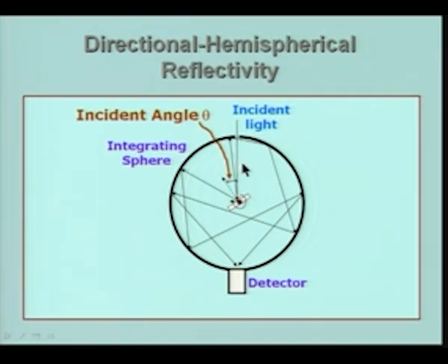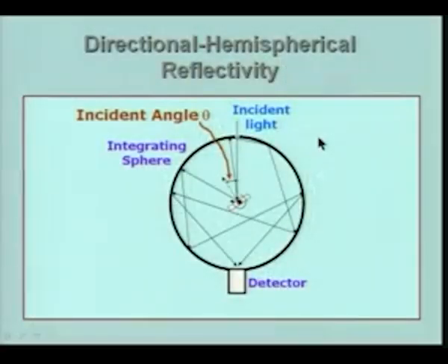Of course, in this case the absorptivity will be the directional hemispherical absorptivity, or in the previous case it will be the hemispherical directional absorptivity, because absorptivity plus reflectivity must be equal to 1 for an opaque surface. We are not going to consider translucent or semi transparent media, because that is somewhat more involved and we will avoid that.